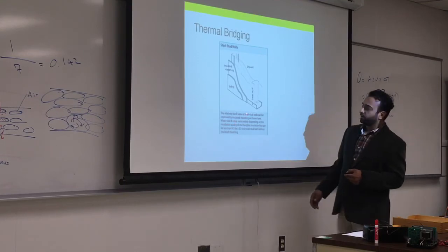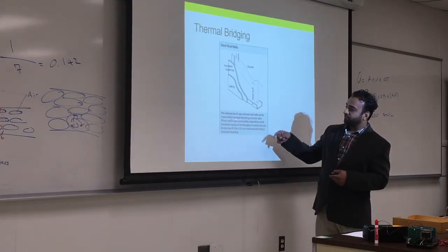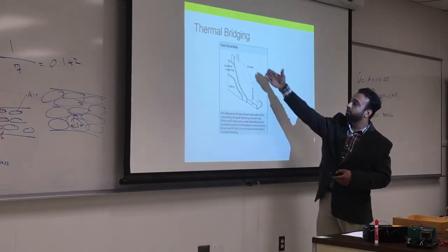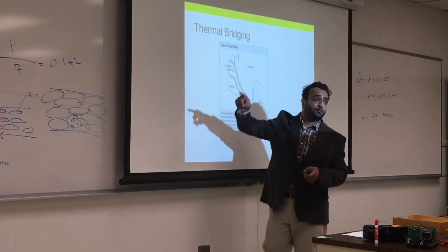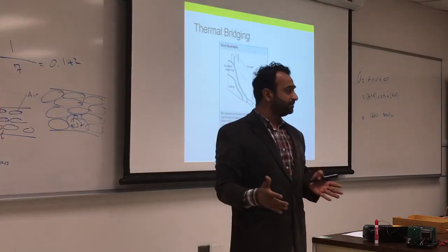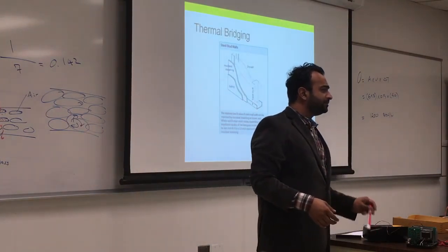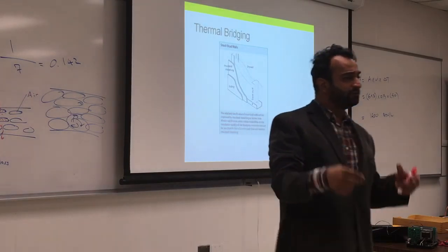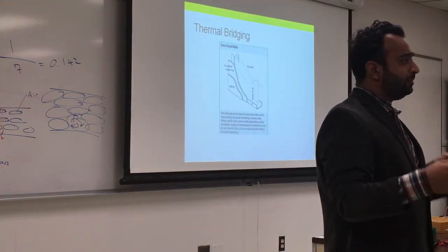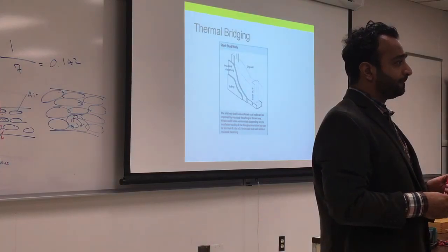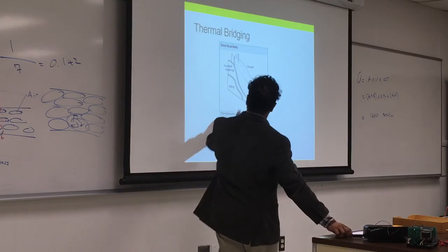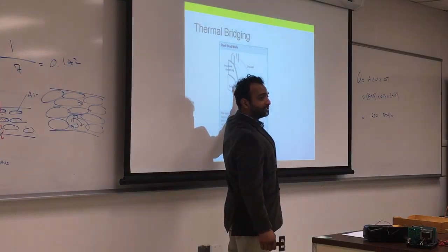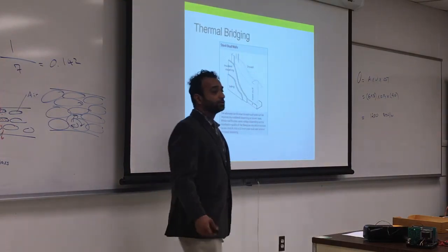The typical low R value of steel studs can be improved by insulating the sheeting as shown. So there is no way around conducting heat from the studs. Steel studs are better when they are in H or I shape. Is that what's called an I-beam? The I-beams have a pretty small surface to conduct through in the middle, but you're still going to conduct part because it's metal. So if you don't have a good thermal barrier, like the proper sheeting here and proper drywall, you will probably lose a lot of heat through the wall.